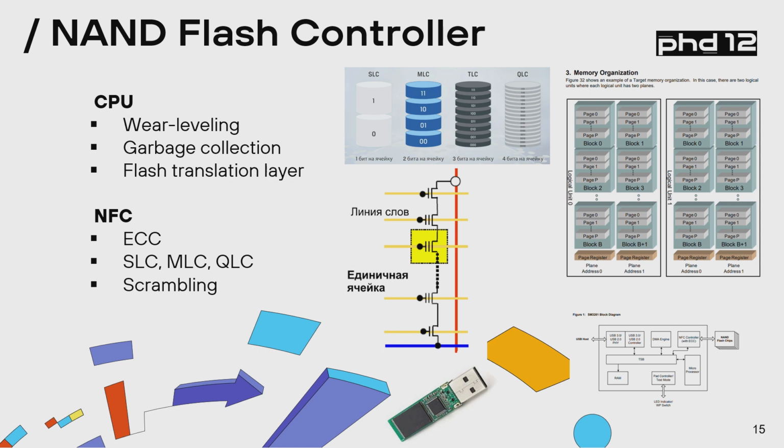Moreover, in your microprocessor kernel, you will also need to support the flash translation layer. So you need to convert addresses into real physical ones. And NAND is by far non-linear because it's composed of units of blocks, and blocks of pages, and pages of chunks. Moreover, units can be put together to form abstractions. So you need to store all this information in table form, I assume, somewhere in the memory.